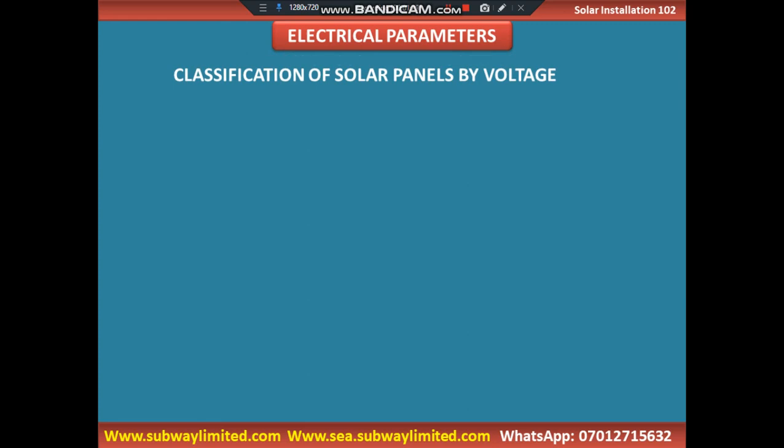No, we don't have a 50 volt solar panel. That is the open circuit voltage of that solar panel, as we will make you understand in the course of this training. So when you look at any solar panel, basically we have two types of solar panel when we are considering the voltage of a solar panel.